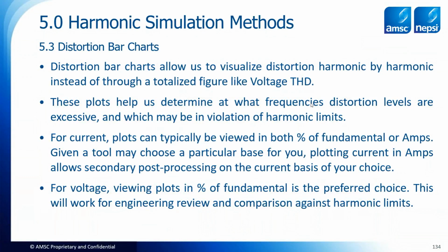Now, for voltages, that's fine, but for currents, I recommend using amps and not percent of fundamental, just because if you ever want to do any post-processing, you can put these amps on any basis that you want. And that's particularly important when you're coming to IEEE 519 compliance, and you have a base that has to be applied according to the standard. Then putting them out in amps is more useful.